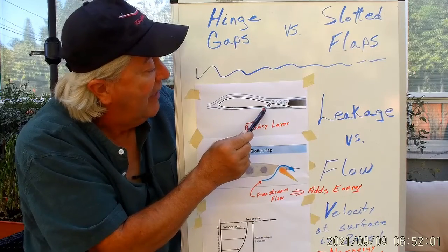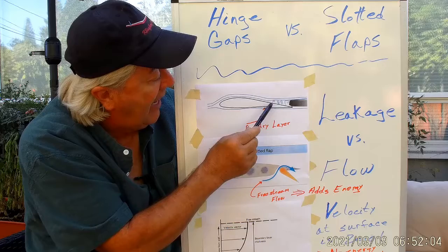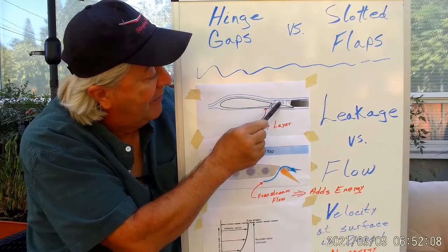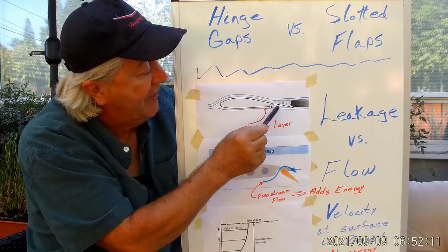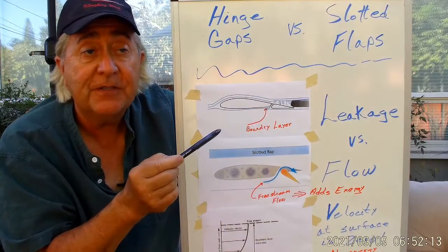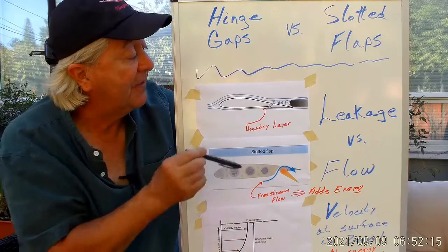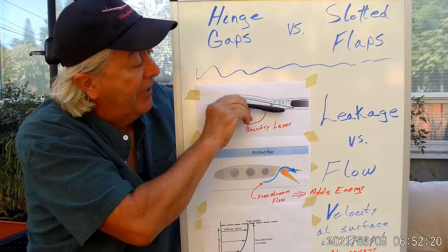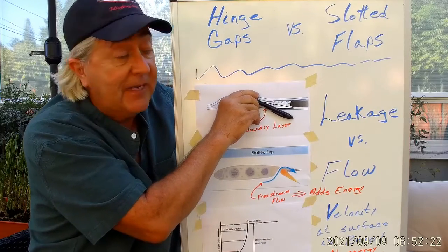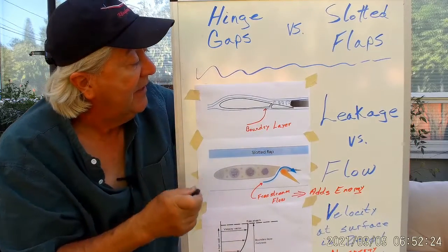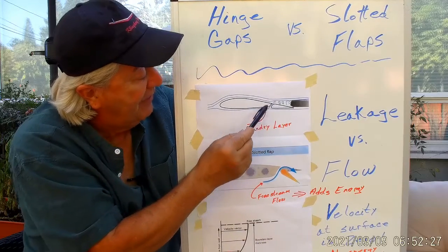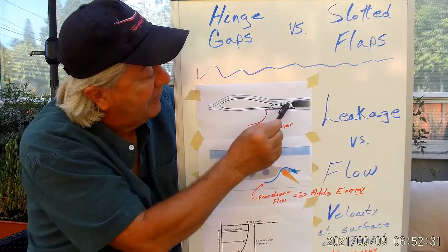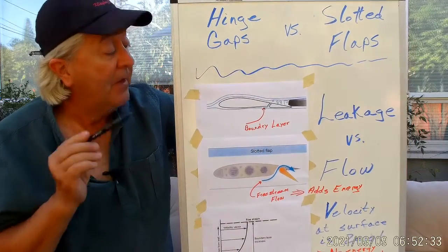I've solved it now. The air is going through the gap between the control surface and the main wing panel, and it's becoming turbulent here above the control surface, rendering the control surface mostly ineffective at certain angles of attack. Now this is shown with the control surface not deflected, but mine's only showing up at significant angles of attack, something beyond 10 degrees on the control surface. But you have the basic concept here, that it is leaking through and causing this flow to separate from the control surface.